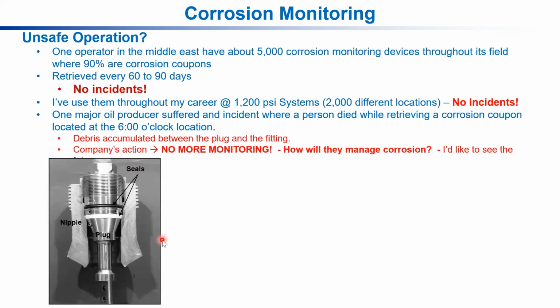Here is the case. This is the plug, this is what you remove, you take in and out, and this is the fitting. By the way, I just want to make a comment. It is very important to avoid issues also with the fitting, that every time you remove this plug, replace the O-ring and replace the Teflon. Those are the seals. It doesn't cost much to replace them. Replace them because that is the life that is going to avoid leaks outside.